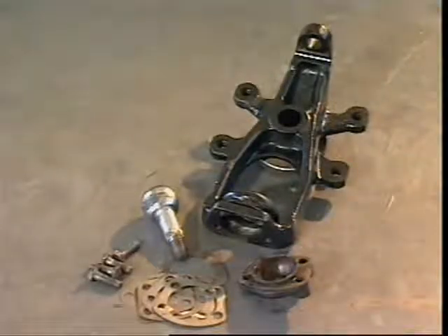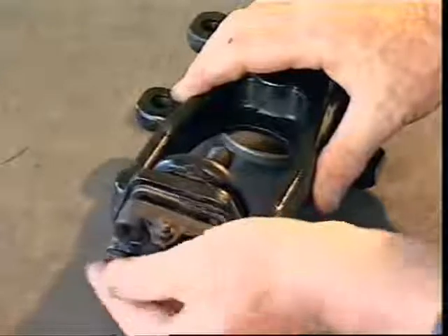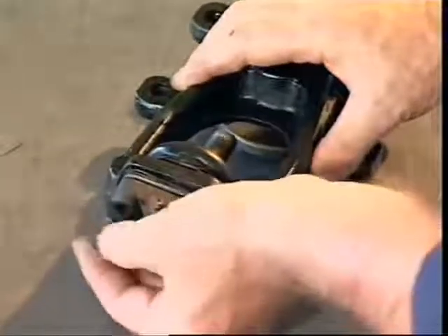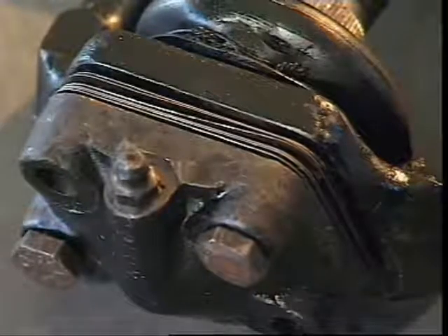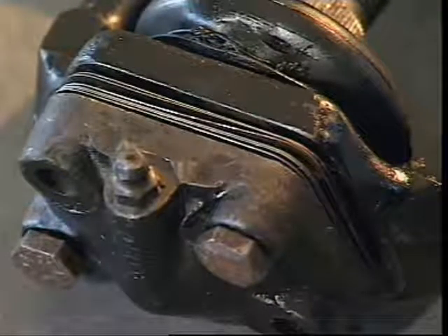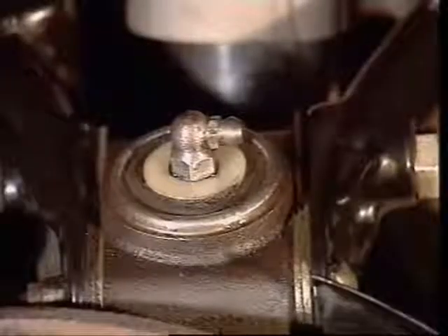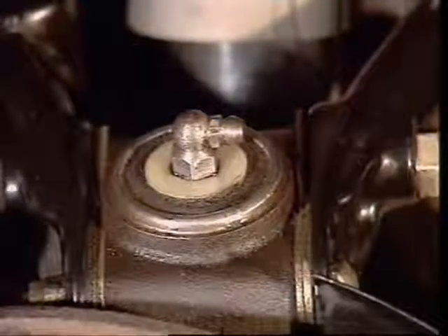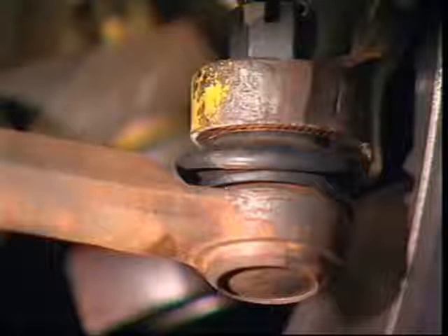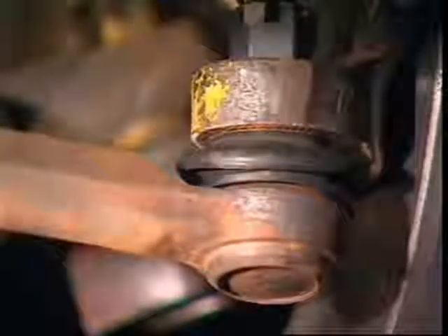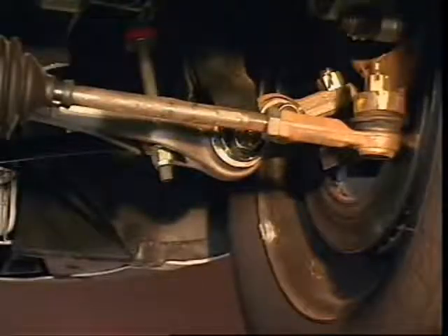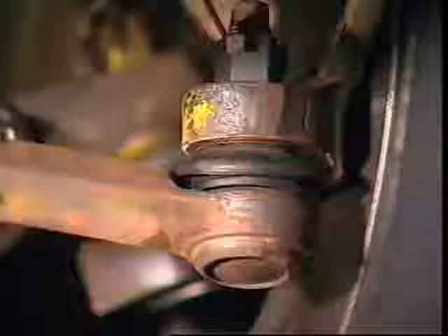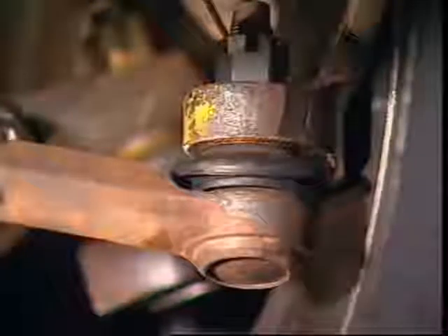Some ball joints can be dismantled to replace the seats and the ball stud and allow for adjustments. Shims between the upper and lower halves of the joint allow free play to be controlled. Grease nipples can allow for periodic lubrication, but most joints today are sealed for life, and no regular maintenance is required. On tie rod ends, the ball joint is usually self-contained and attached to the tie rod by internal or external threads.